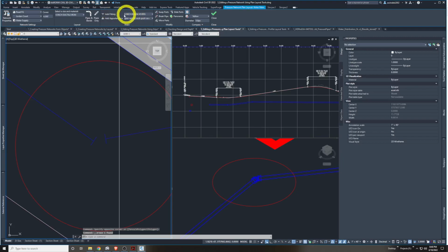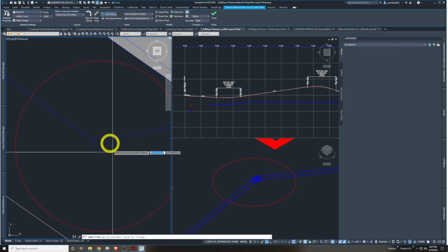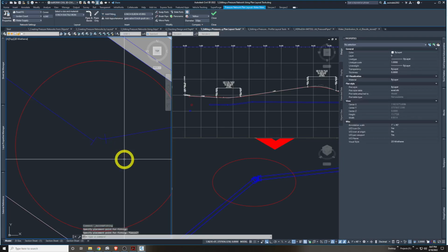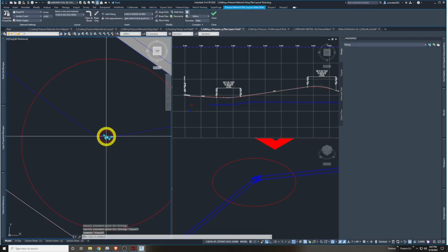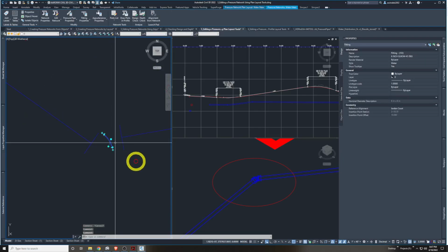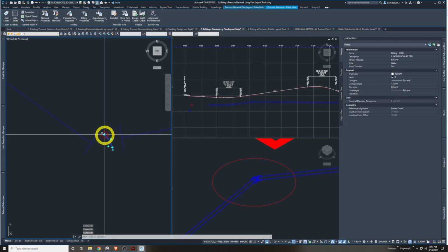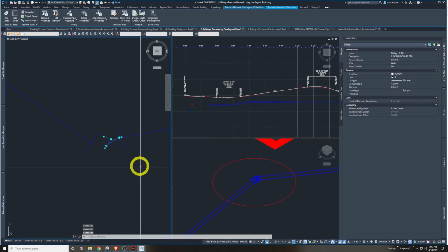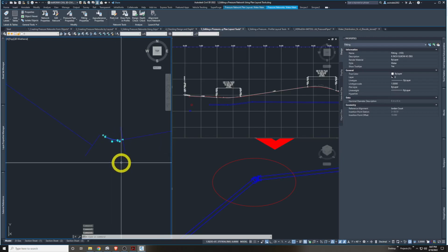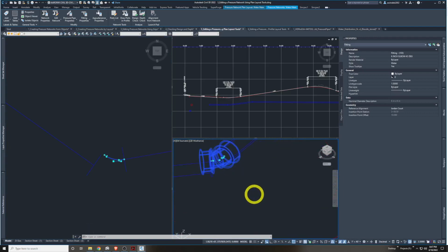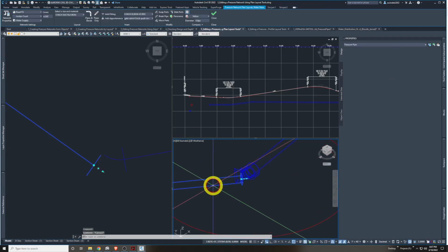Let's add a fitting now that we have the right things selected up here, the material and the cover, these various things. That's key. Let's say add fitting. I got that end. Let's hit escape twice. Get out of that command. Let's take this and flip it. Okay, we have a few directions to flip it. I did one too many. That should work. So it's looking like that. There's a few directions to flip it for both sides. It's getting close. We just need to connect this pipe now.